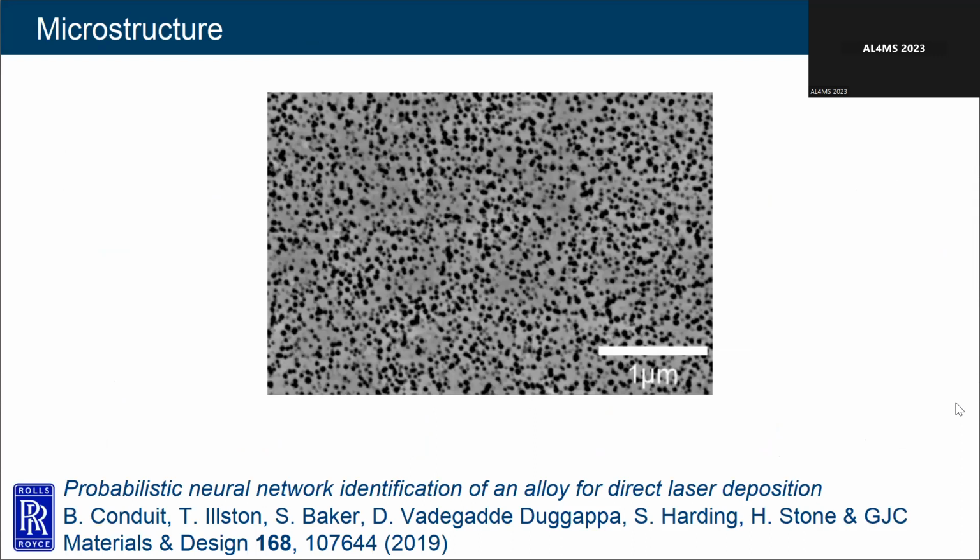This is what it looks like under a microscope. You can see that it's got some gray and some black. So it's a two-phase alloy. The black are some precipitates that are formed in it. We can measure what those precipitates are. We can measure their size to make sure they are what we expected and are required in order to make this what is called in the field not just an alloy, but actually a superalloy, due to its promise of excellent properties at high temperature.